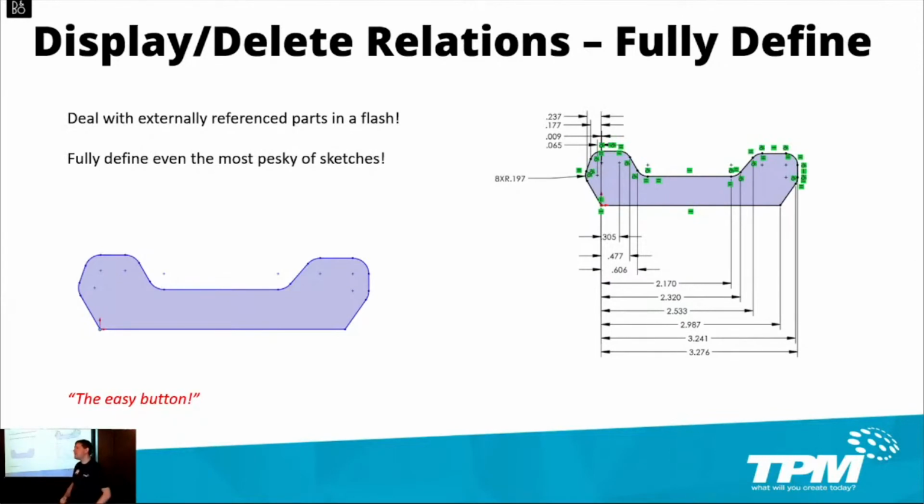Yep. Yeah, just when you're drawing something, you normally, if you want a 30-degree angle, you're going to dimension it as 30 degrees. Right. You're going to dimension it as half the height versus the width. Right. You know, you're going to dimension 30 degrees, and then you're going to dimension one leg of the triangle. And in this case, there was a fillet on both sides, so there were no reference sketches, right? Because I had just a face to begin. So yeah, use this tool as you guys see fit. I do like this. It's what I call the easy button when I'm using this.